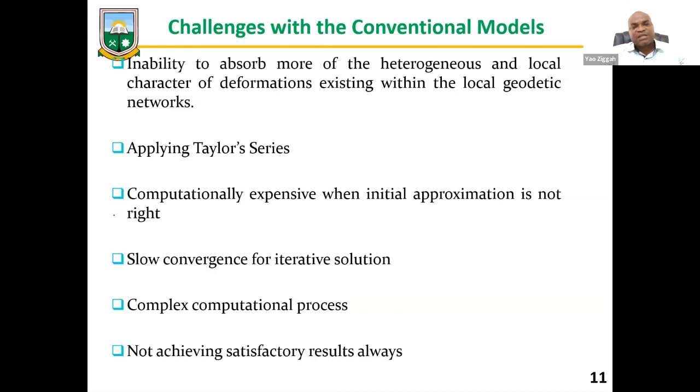Now, when you look at these two different surveying techniques, different personnel, different equipment, and different assumptions, when you put these two methods together to form the network, this gives you distortion. And that is why one of the key factors to consider when you are applying any transformation model is to understand where the distortion is coming from.